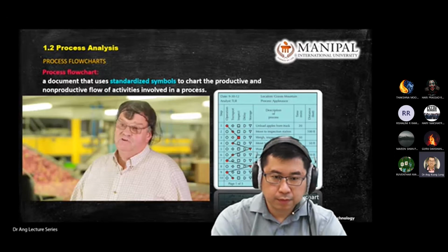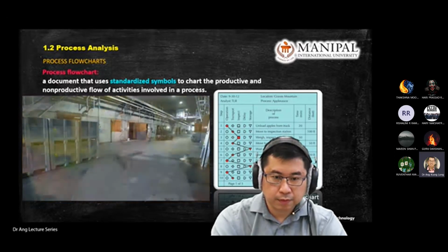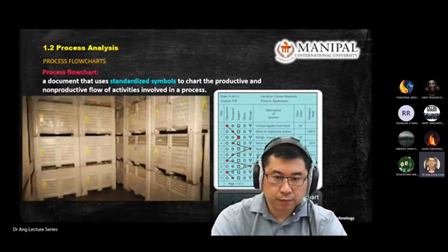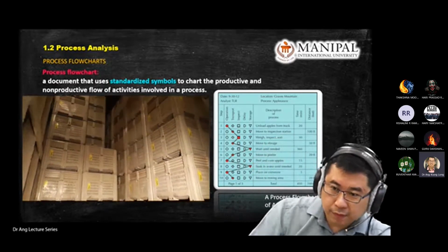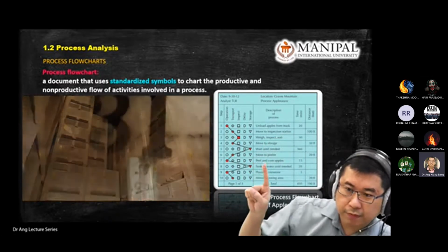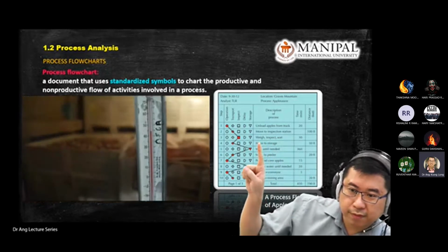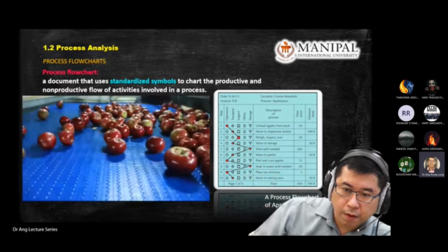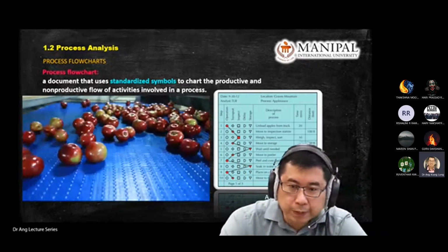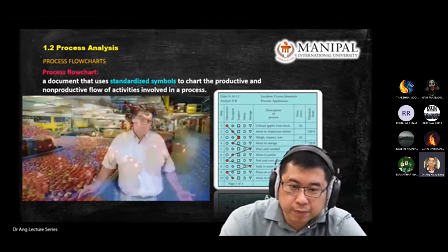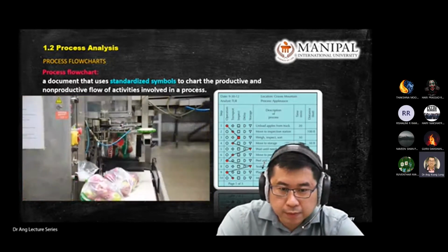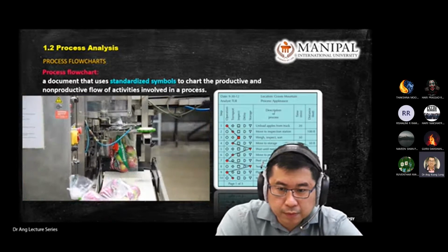The key to making them stay fresh is to pick them at the right time, and then we put them into storage rooms where we control the atmosphere. An apple breathes carbon dioxide out and oxygen in. So we reduce the oxygen level in a room to suppress the respiration of the fruit, basically put them to sleep, and then keep them that way until we're ready to pack them. And then we would put oxygen back in the room by just putting air in it, bring the apples back awake, and then we pack them and send them to the grocery store.